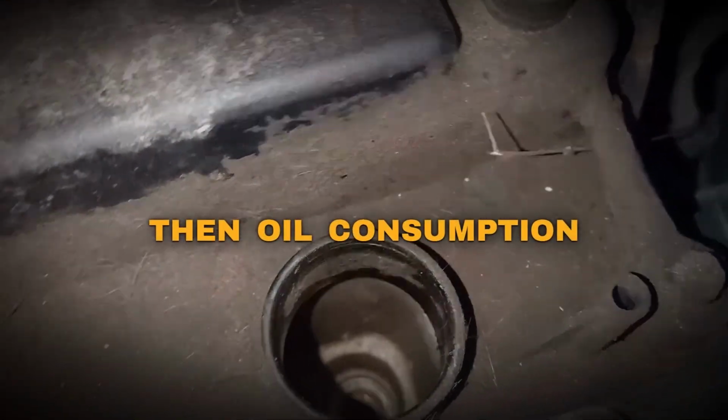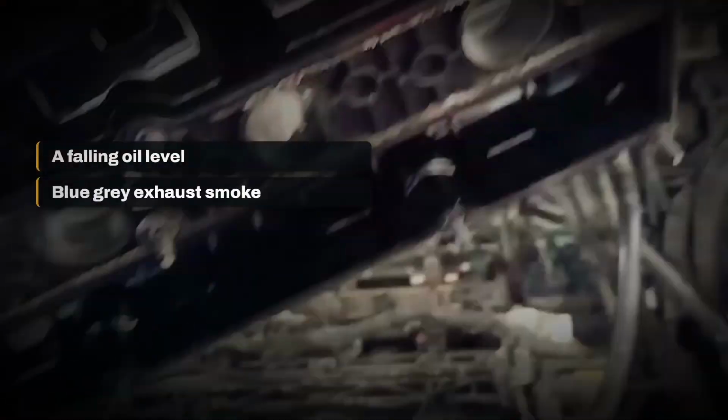Then consider oil consumption. An engine that burns oil can contaminate the converter over time. Look for a falling oil level, blue-gray exhaust smoke, oily spark plugs, or a documented oil consumption problem.